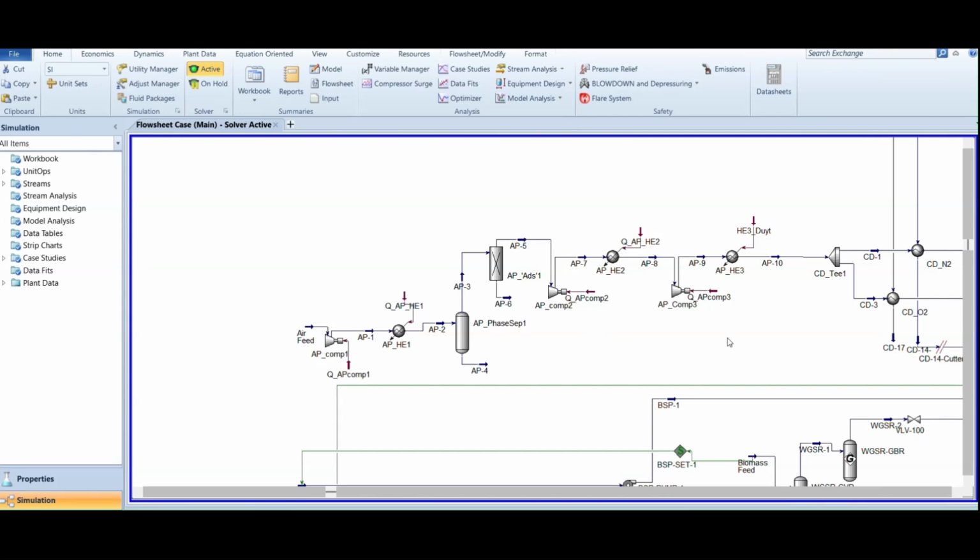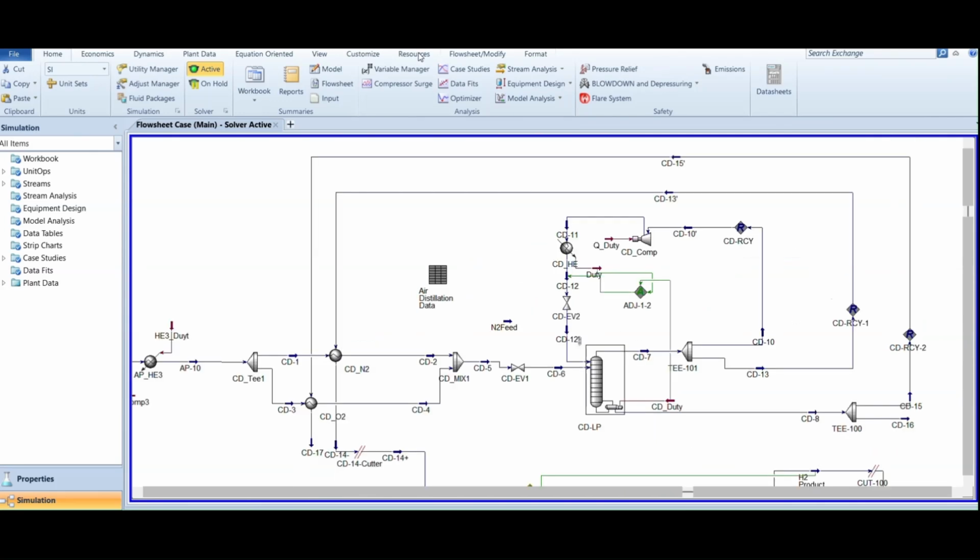Then air is compressed up to 40 atmospheres in 2 steps. To efficiently reach the cold needed for the cryogenic distillation, the feed to the column should be pre-chilled. Through an energy integration, it is possible to use the cold from the outlet streams from the distillation column to pre-chill the feed to the column. It is important to do correctly the mass balances on these component splitters so the temperatures do not cross in